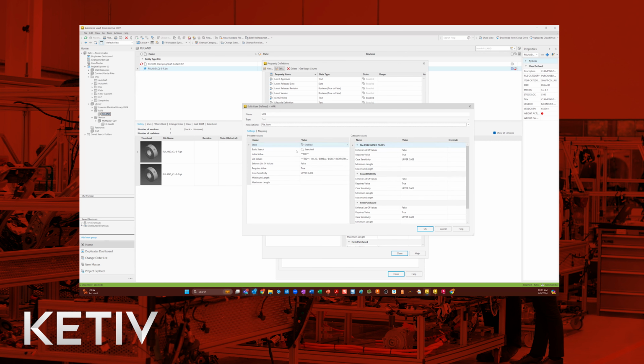In the property values here is where you have a lot of control, pretty much potentially forcing your users to comply here. So you can start by having an initial value. You can, like I did here, create a pick list with various values. I just did some common manufacturers that I used in the past here. You can tell it to enforce the list of values, so that will make it so the user cannot manually enter another option here. They are forced to utilize only picking from this list here.